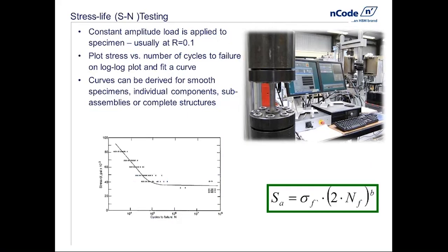So how do we approach this? In the middle of the 19th century, when August Wöhler first implicated, or, I can't think of the correct word to use at the moment, but identified fatigue as a means of failure in railway axles, he set forth by thinking, well, I can mimic this in the lab. I'll get a bar of the material, I'll rotate it, and I'll hang a load off the end. And that's exactly and precisely what he did. Those are rotating bending specimens. And basically he had a series of different loads and would calculate a stress on the basis of those.